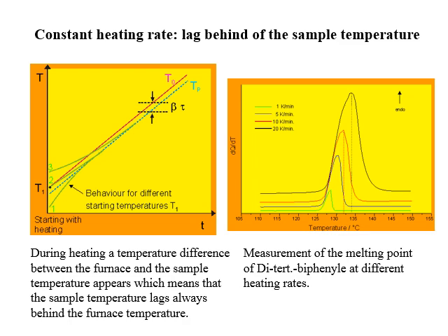What does that mean? It means generally in the TGA curve, you want to heat as slowly as possible. But obviously if you're doing a TGA curve and starting from 30 degrees centigrade and going to 1000 degrees centigrade, if you're doing it at 1 degree a minute, that would be a 970 minute scan. A typical or common ramp rate in TGA is generally 10 degrees to 20 degrees a minute.